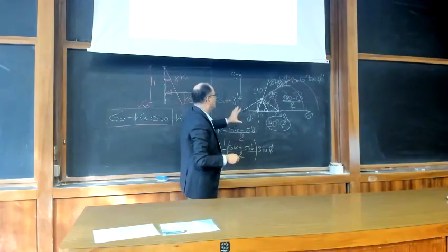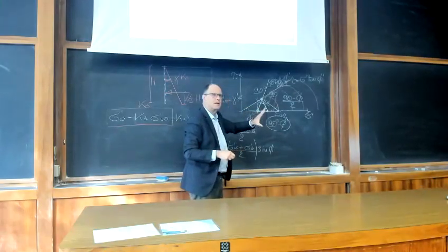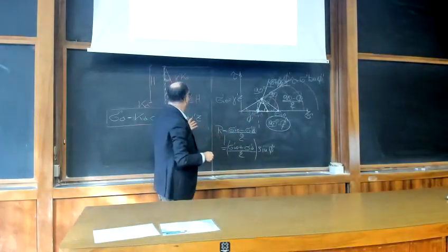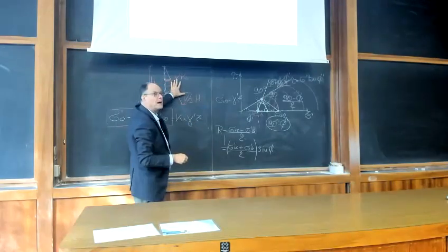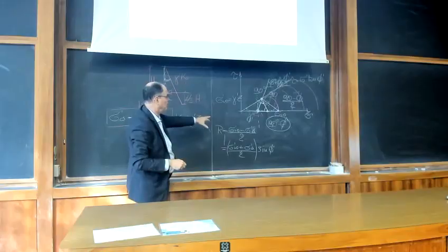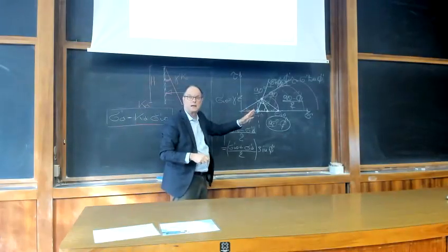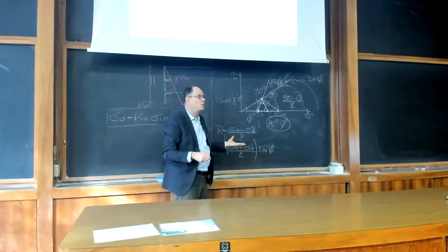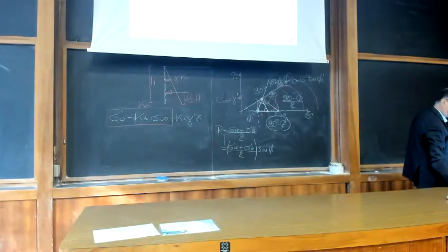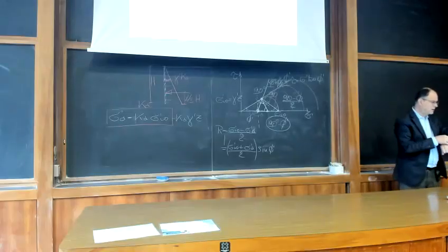Okay? But of course, this is the Rankine theory behind it. In a way, we have solved the problem. Under the Rankine assumptions, we know how to calculate the active pressure, and it is relatively simple. We have just one further step, in the same way. Before this further step, let's also have a look at this Rankine limit state of stress.